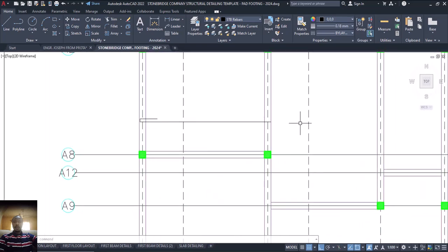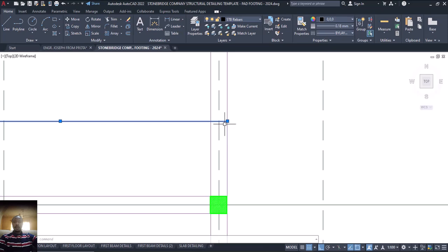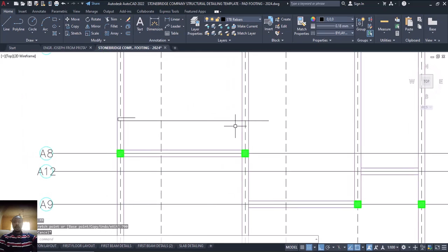So that is fine. Now in this lapping, we discover that we are using a Y12. Is that okay? This Y12, now the lapping at this point will be what? 600. I always use what? 700. Is that okay? For lapping. So that's that. If it's a Y16, it will be different. Is that okay? So that is that.